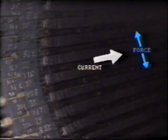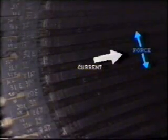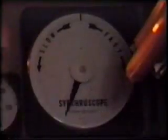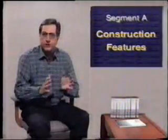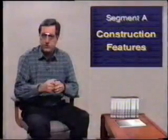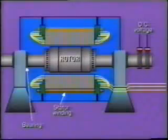This is extremely important, as the windings themselves are subject to quite heavy mechanical forces during operation. The windings may try to twist during heavy power surges or electrical faults on the power system. Similar distortion of the windings may occur if the generator is badly synchronized, that is, synchronized when out of phase with the system. One of the few problems that can occur on generators is the loosening of the windings, with resultant vibration and increased temperature rise and perhaps damage to insulation.